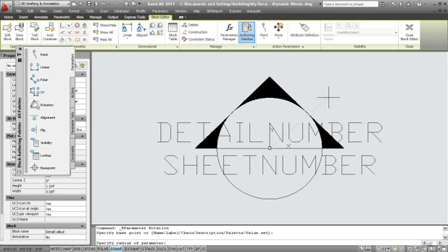Radius. This is basically just for reference. This isn't going to control what you can or can't do, but I typically pull this outside the block. It just makes it a little bit easier visually to deal with once we actually get this control in there. So I'm going to click here. Default rotation angle, I'm going to just leave this as 0, so I'm going to hit enter. You'll notice I get what is going to become a control point right here that will allow me to rotate whatever objects I select.